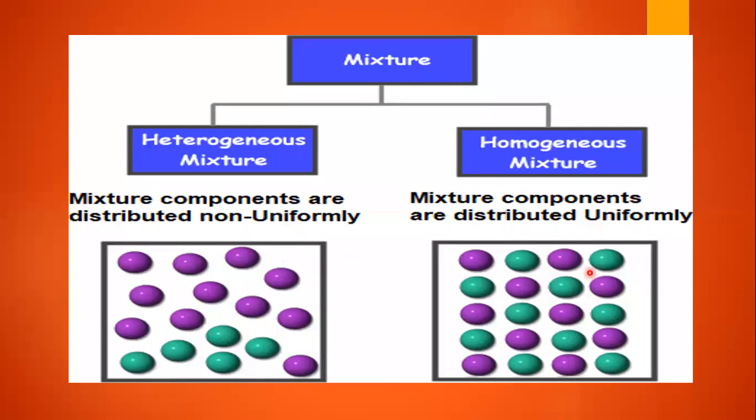In a homogeneous mixture, we need to talk about the stoichiometric mixture and the equivalence ratio. What is a stoichiometric mixture? To burn 1 kg of fuel completely, we need a certain amount of air. Majorly we take a 1:15 ratio, that means 1 kg of fuel to 15 kg of air. That is the stoichiometric mixture.